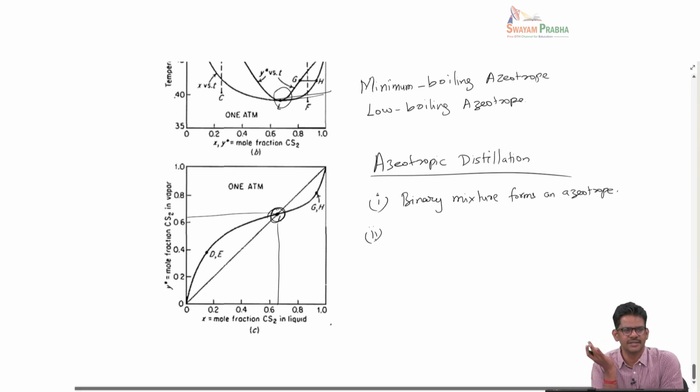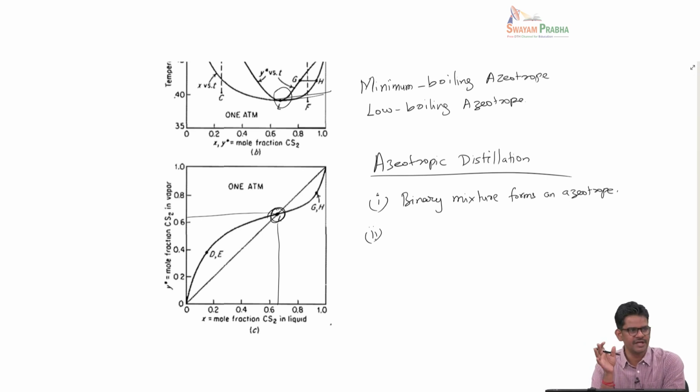Why there is an azeotrope, whether an azeotrope will always form, these are all determined by thermodynamics, purely thermodynamics, which encodes the mutual interactions and ideality and non-ideality of the constituents. And the azeotrope may be present at certain temperature and pressure, and it may vanish at another pressure. So you have to look in detail at what the thermodynamics will tell about this binary mixture. Okay. So there are compositions that we know. A very well known example is the ethanol water system. It forms an azeotrope at 89.4%. Okay. So beyond that, the purification is very difficult.